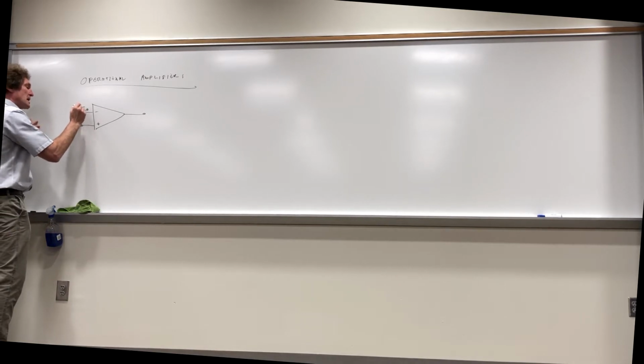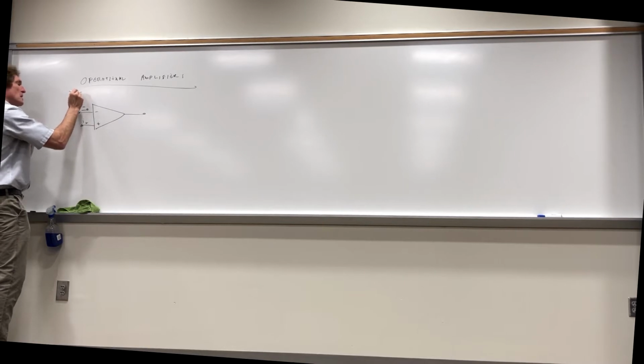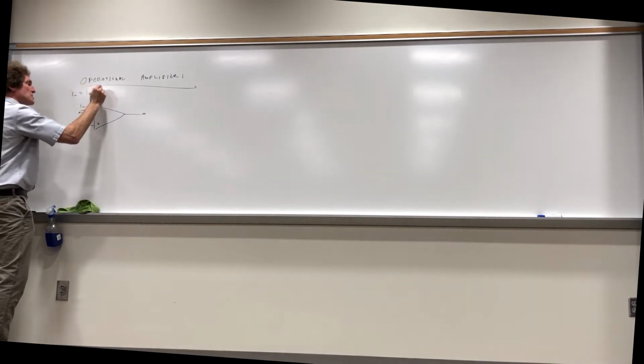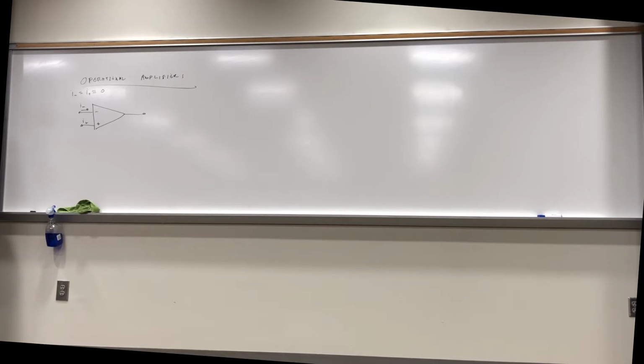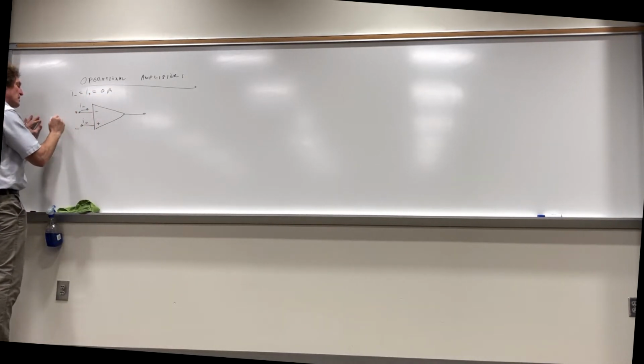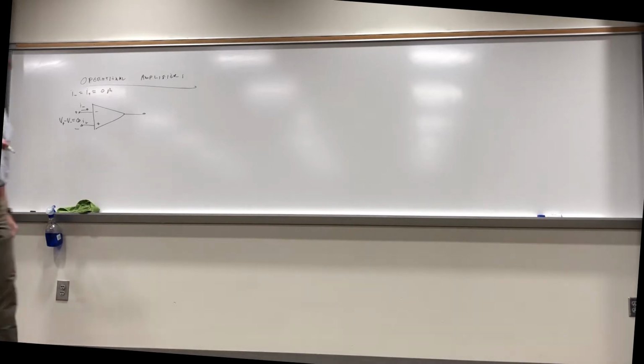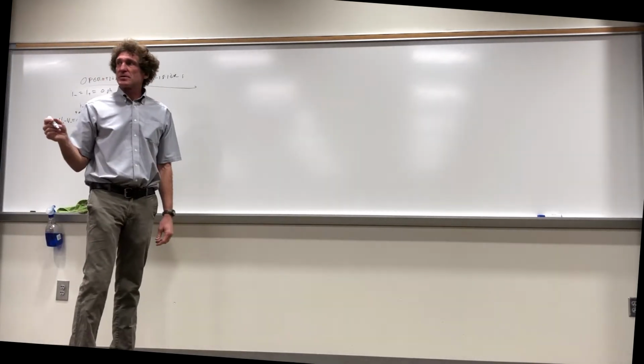So I negative, I positive, both equal 0 amps. And the voltage difference here, V plus minus V minus, is 0 volts as well. So there's no voltage across those, no current into them. The way this happens is electronically it's forced to do this. Everybody with me, class?